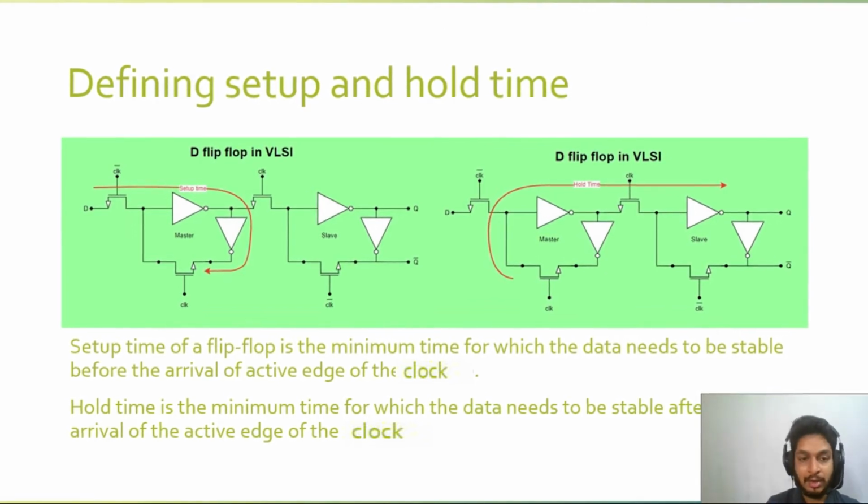I'll show one scenario later. Setup time is related to the flip-flop itself, and is only defined for the synchronous flip-flop, right? For the latch it is different. For latch, we say removal and recovery time.